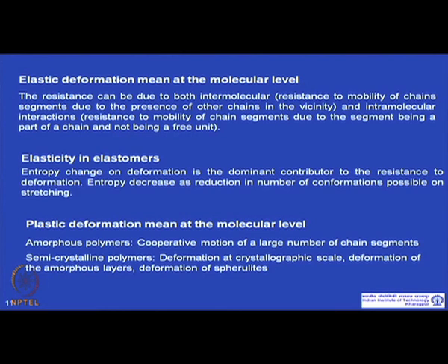And in the case of plastic deformation in polymers, especially amorphous polymers, a large number of chain segments move cooperatively together with each other. In semi-crystalline polymers, there is deformation at the crystallographic scale, in the crystal state.